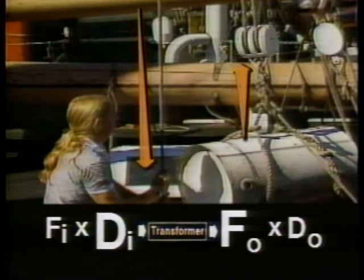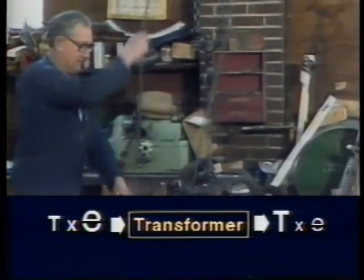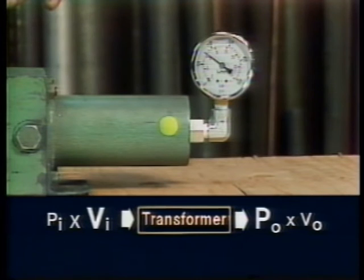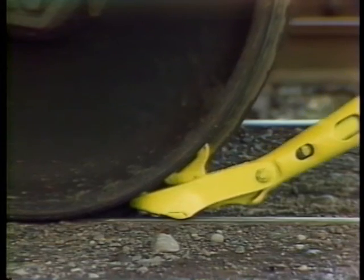So in a mechanical linear transformer, distance is decreased to increase force. In the rotational mechanical system, angular distance is reduced to increase torque. In the fluid system, volume is sacrificed for the sake of pressure. And in the electrical system, current is reduced when voltage is stepped up.